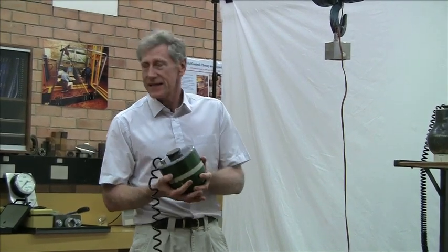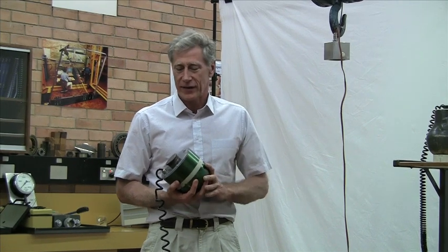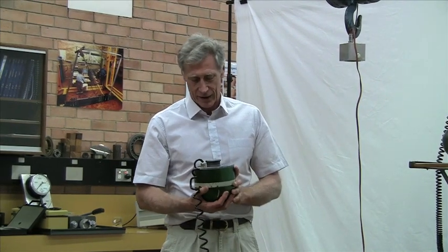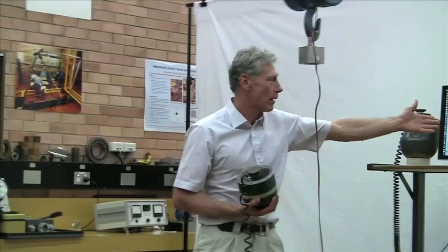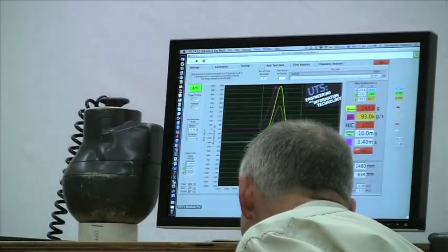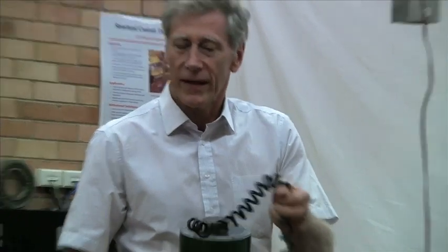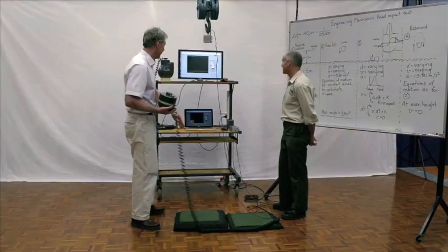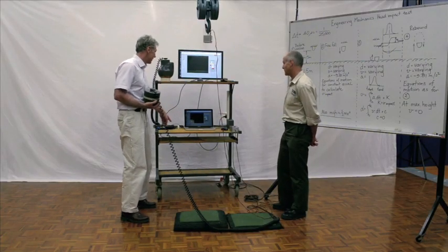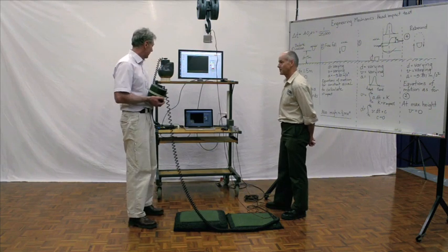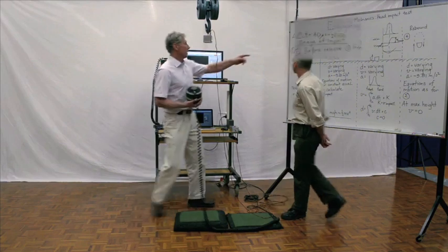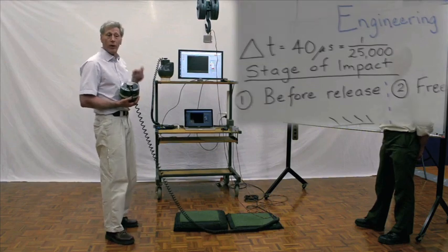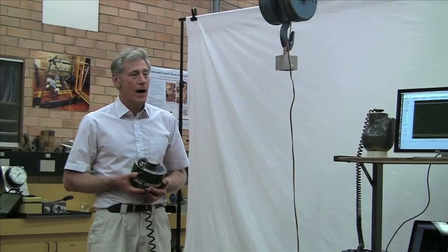And they're basically strain gauges. They measure the strain when an acceleration or a negative acceleration occurs, and we get an output on the screen here. It's really a voltage. So when they're strained, we produce a voltage, and the voltage travels along this umbilical cord into a data acquisition system in the USB port of the computer. We sample at 25,000 samples per second for each channel, so every 40 microseconds.